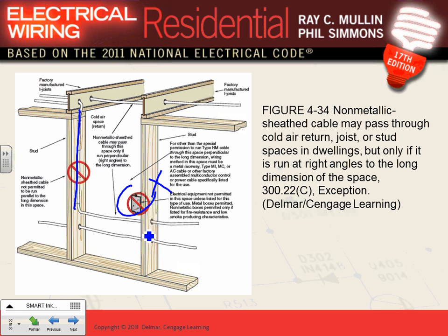And another thing is, now this is your return. If you have a fire here, you're basically pulling the fire into the furnace and spreading the fire through the whole building. There's a whole lot of fire issues that we don't want. If you're going across, you almost have to, because you go from point to point. But going up, you have alternatives, right? You can go across and then go up. Sometimes going across, you have to, because it's the only way you can go from point A to point B. Going up, you can always cross and go from another direction. So it spreads the fire, and the other part, of course, is you don't want to expose the conductor to higher temperature than it's needed.